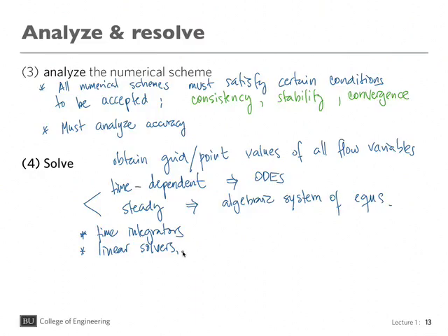The discretization method consists of the geometrical part, how we're going to discretize the space, and the scheme itself: finite difference, finite element, finite volume, spectral methods. We need to be aware of the analysis, convergence, stability, and consistency of the numerical method. We need to know how to analyze the accuracy, how to measure the errors of a simulation. There are techniques for that, and you need to know how to verify and validate your methods, your numerical calculations.